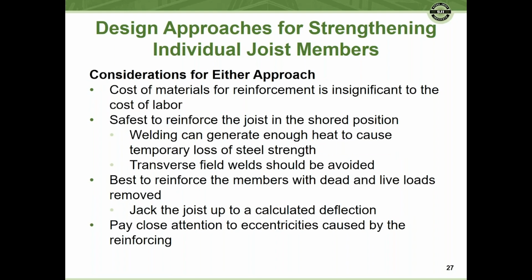So in either case, we need to look at a couple of things. First, the cost of the materials for reinforcement is insignificant when we compare it to the cost of the labor. So typically, what we try to do is make the reinforcing material as uniform as possible. It is safest to reinforce the joist in a shored position. Welding can generate enough heat to cause temporary loss of the steel strength, and transverse field welds should be avoided.